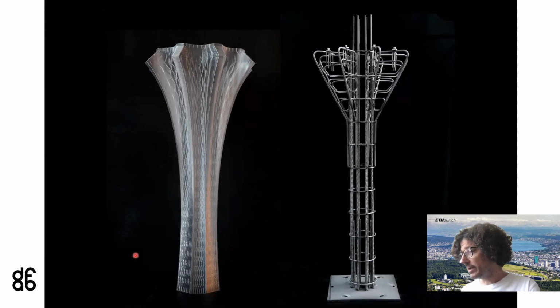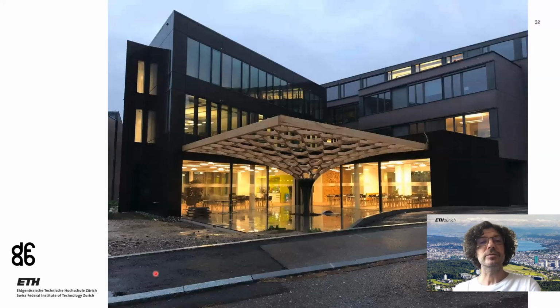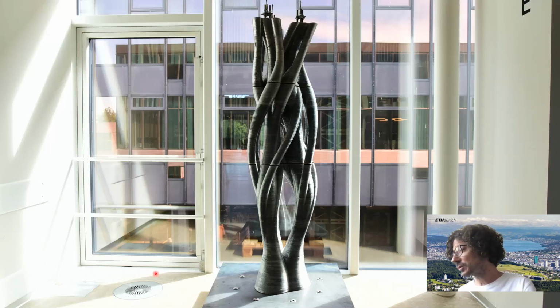Now, this object here is a concrete column, produced in our lab, and serving as a base for this future tree, a pavilion at the renovated headquarters of the engineering company Basler and Hofmann near Zürich in Switzerland. The same type of process has been used to create this exotic post-tensioned structure out of 3 elements, and I like to show this object to underline the geometrical complexity that this 3D printing of a formwork allows us to access with concrete. However, this 3D printing of a formwork takes time, and you might argue that it also generates its load of waste. So let's look at even easier systems.